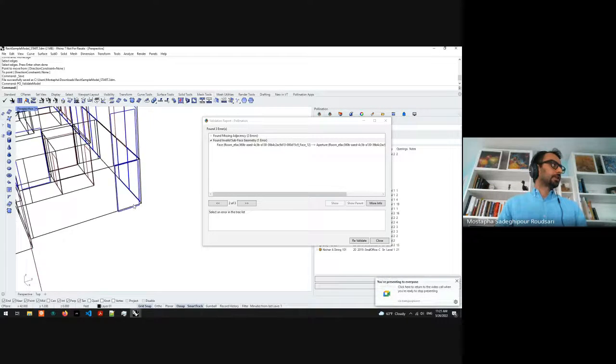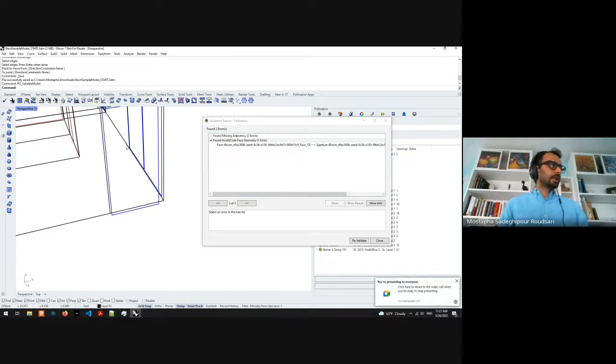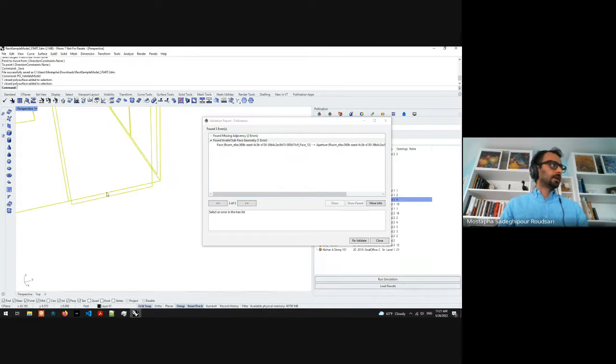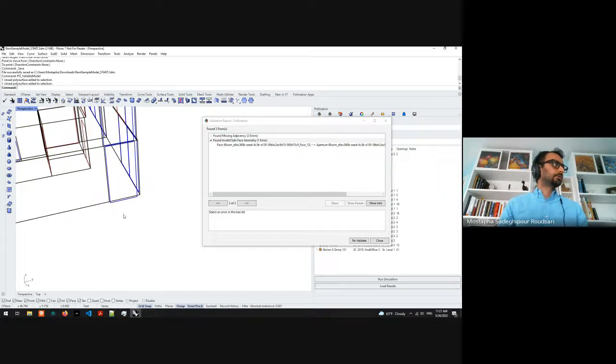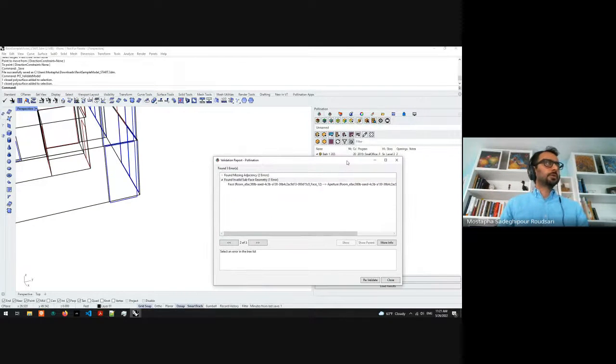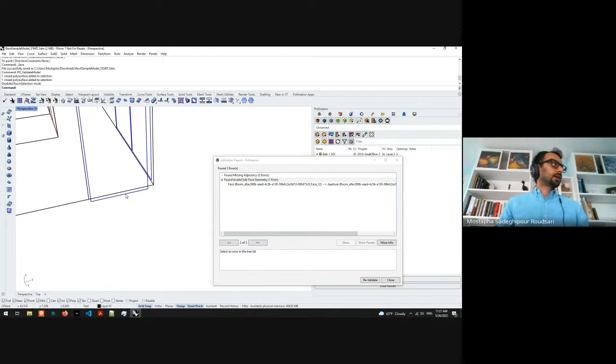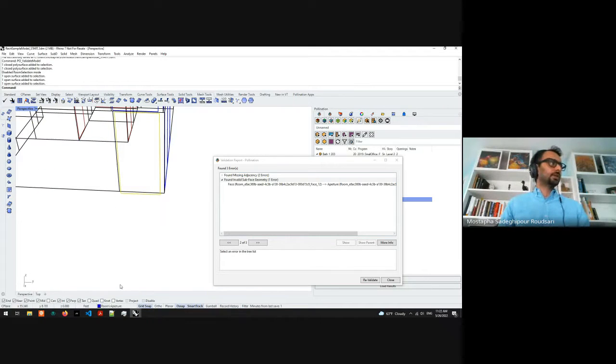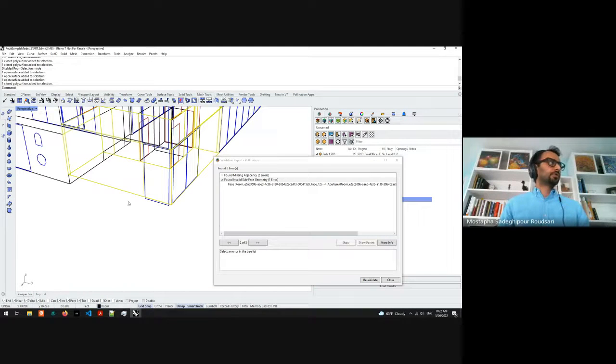I already zoomed. Let me try to fix it. The way to fix it is to move this edge up, right? And when I try to do it, it won't work because everything is a room. I won't have access to that edge of the window; I can only select the whole room. So how do I make that work? There are 2 different ways. One is I go here and turn off the room selection. When I turn off the room selection, now I can access these child objects directly. Do this only if you know what you are doing, because now I can move this window outside, or I can just move this room without moving the windows. So this is for more advanced users.